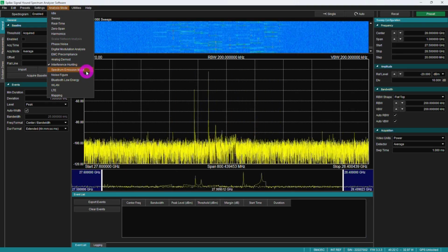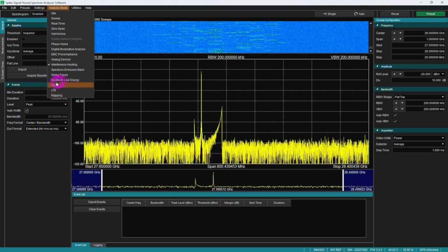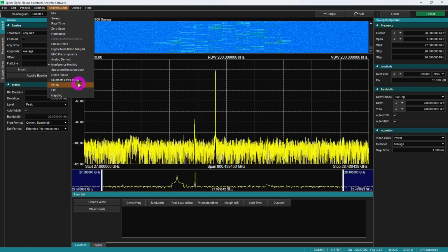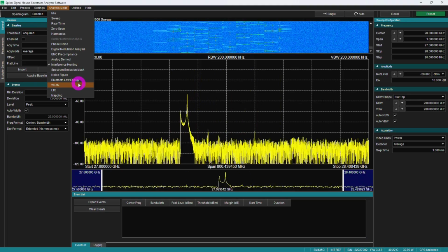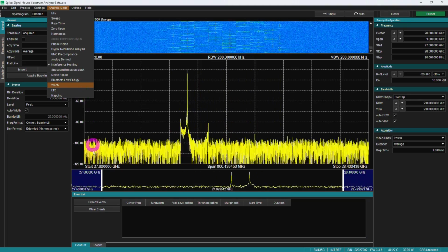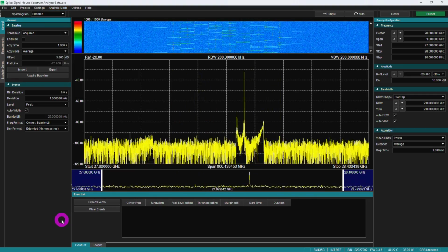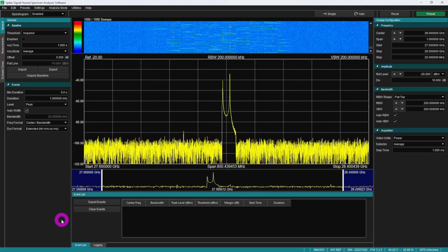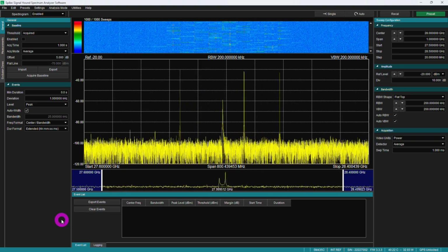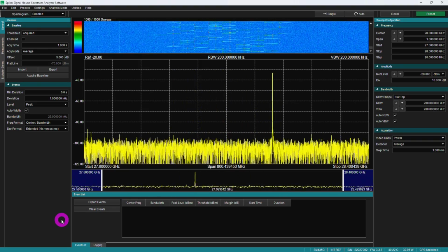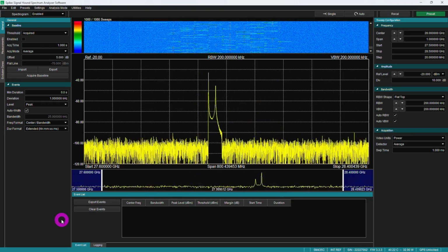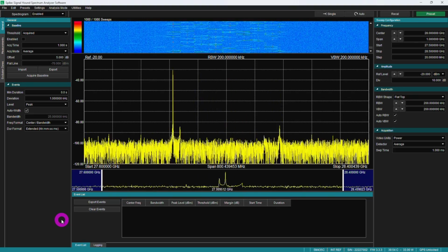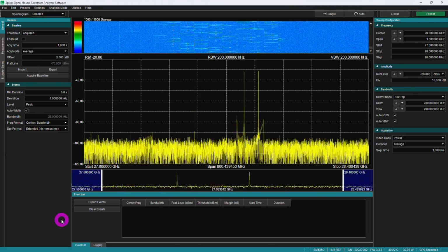And there is a mask emissions you can of course define, and it does have a few demodulations of particular standards in there, and they continue to add new features to it. It would just take forever to go over everything else. And there's recording functions and playback functions, which I showed in the previous video, so I'm not going to go over it again. But in terms of feature set and functionality, in my view, this is basically a dream software-defined radio, especially if you take advantage of the API, grab the data and process it yourself. There's some pretty crazy things you can do with such an instrument with such a fast sweep and so much bandwidth. And there you have it.